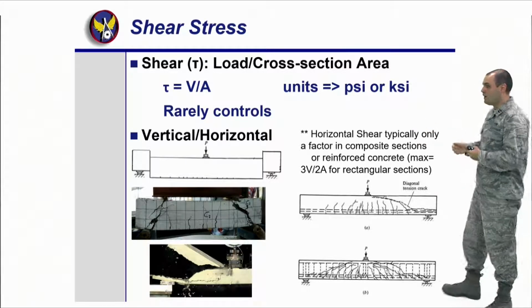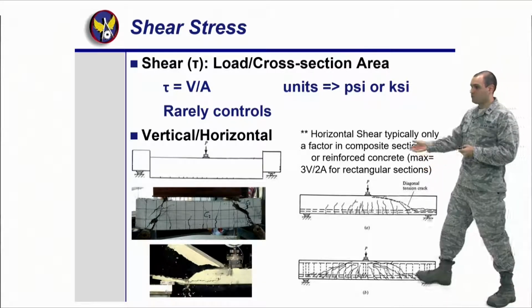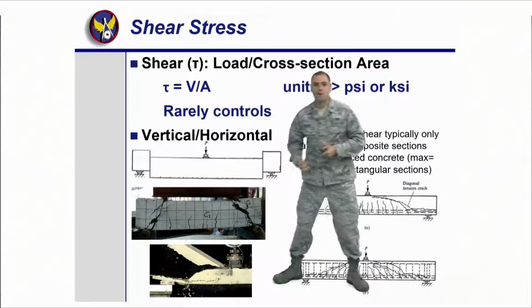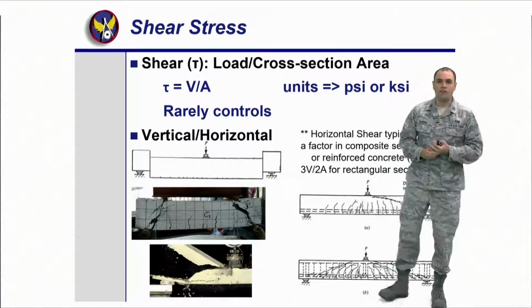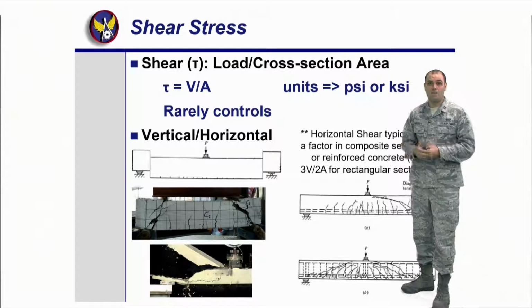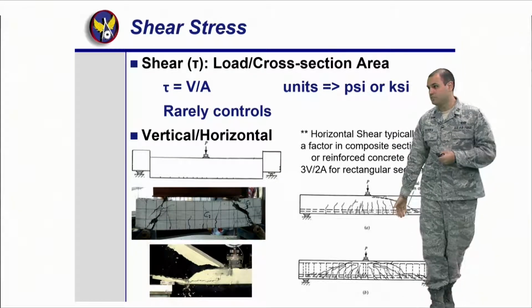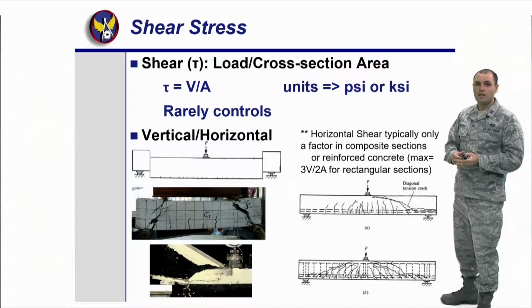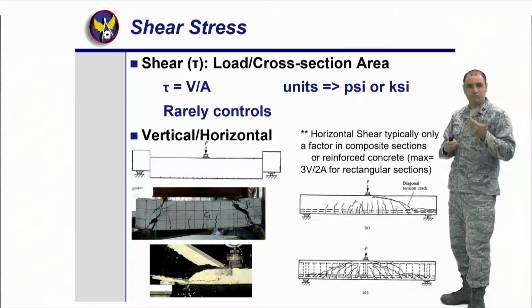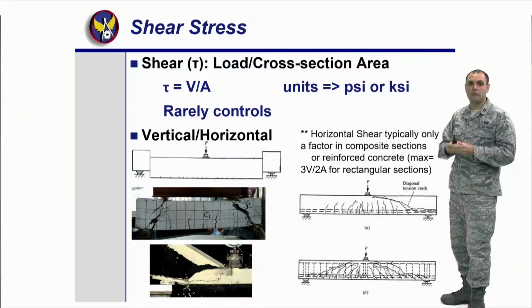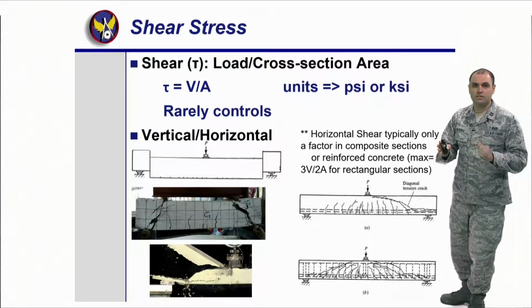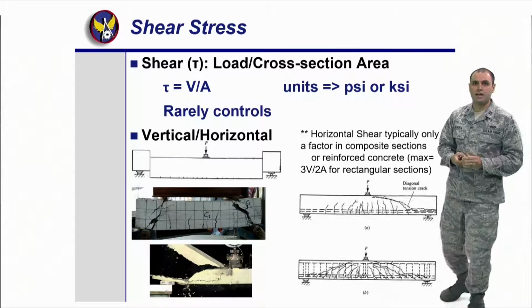the building. This is why I talk about it. You get to see another shear failure here in 3-point load, so you get to see this picture in the bottom. Shear failure is catastrophic, all right? And we need to calculate what it is and make sure that it does not happen. We're going to prefer flexure failure, like I said, in the bottom, because it will give us a little bit of time before it actually fails. Therefore, we can actually go and evacuate the building if we need to, all right? So one thing about shear stress, it's bad. We need to make sure that it doesn't happen.